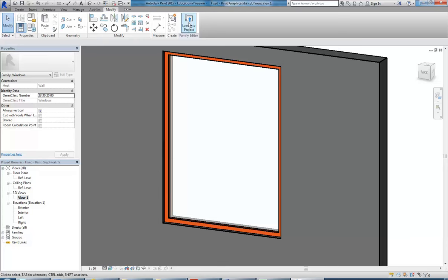Okay, so I want to put some transom pieces in that go across and give me the option of having something on the edge of my floor. So I'm going to go into an exterior view and then just create a new extrusion. Just drawing a rectangle.